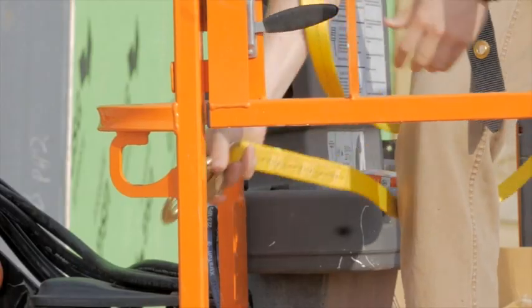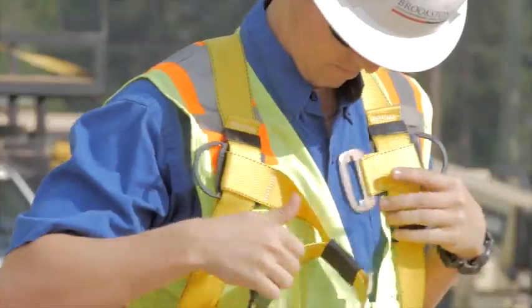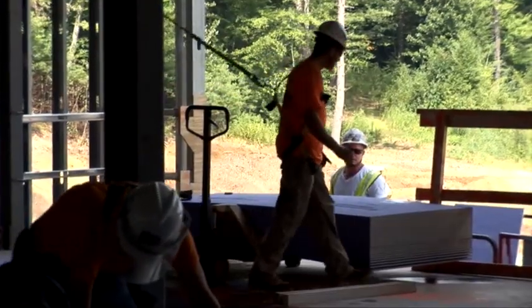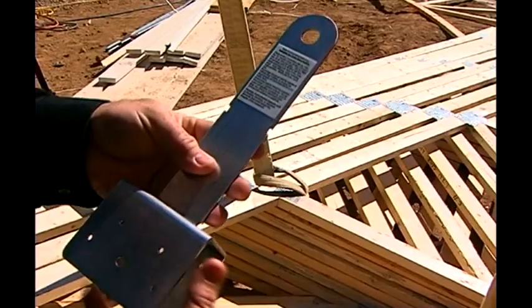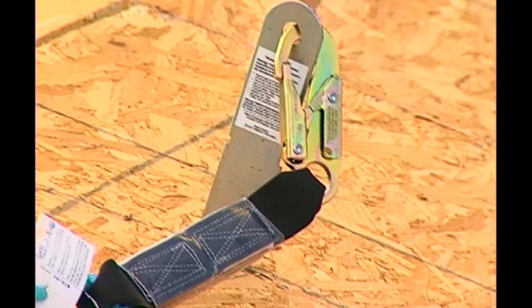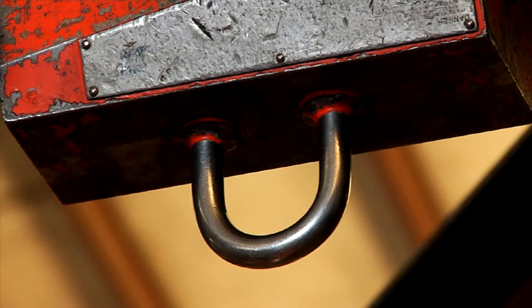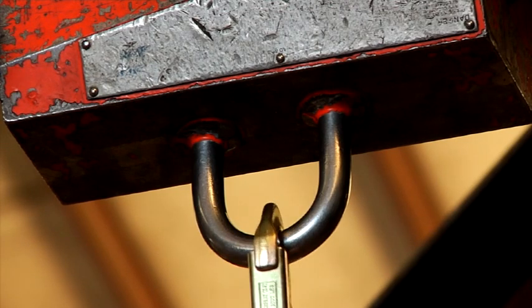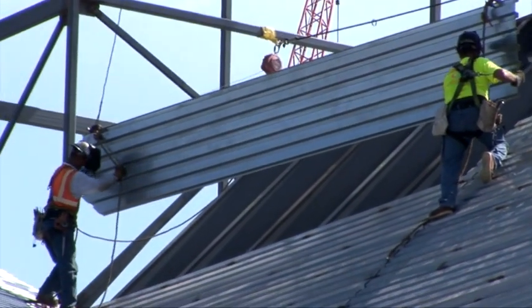Personal fall arrest systems consist of anchorage points, a body harness, lanyards, lifelines, and connectors. An anchorage is a secure point of attachment for lifelines, lanyards, or deceleration devices. Anchorages used for attachment of any PFA equipment must be independent of any anchorage being used to support or suspend